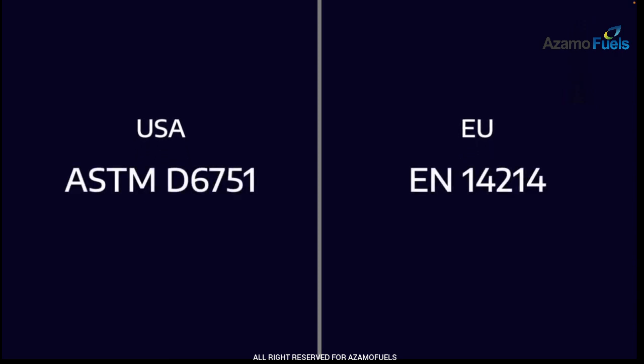So the US and Europe have standards around biodiesel. In the US, you'll see it as ASTM D6751. And in Europe, it's EN 14214, right? That really kind of just sets the standard for what biodiesel has to be. But you really need to look at the engine manufacturers to see, did they design the engines with biodiesel in mind? Or if they didn't design it specifically with biodiesel in mind, have they since tested the use of biodiesel in their engines to ensure that it's not going to cause a lot of damage?